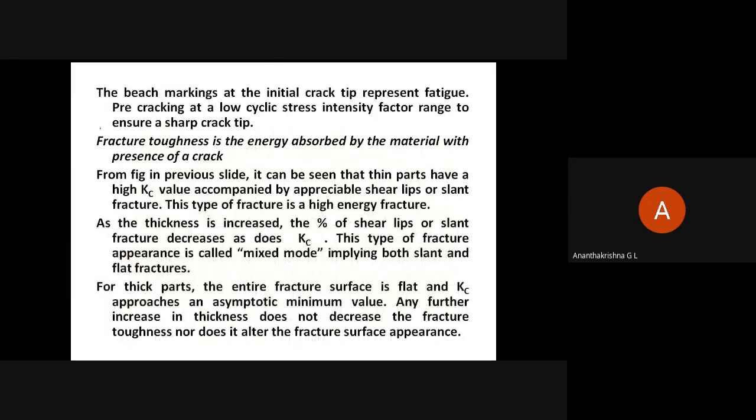And here we've learned that fracture toughness is the energy absorbed by the material with the presence of a crack. So there is some optimal value of thickness beyond which even if you increase it, it does not alter the fracture surface appearance, or it does not decrease the fracture toughness. This is what we learned.